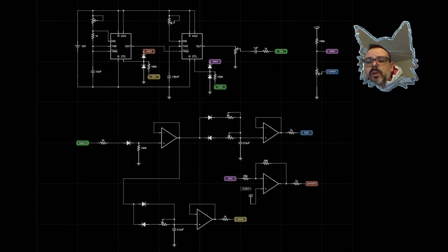The other thing we should consider is having at least some idea of what the module will look like. The reason is that we're going to be laying out components, and if we wait until the very last minute to find out what our module will look like, we may end up having to redo a lot of the work. So it really helps to spend a little time to have an idea of what the module size should be, what the layout of the knobs should be, how many jacks we're going to put in there, whether we need LEDs, whether we need buttons, that sort of thing. Okay, next, let's discuss the high-level PCB design process.